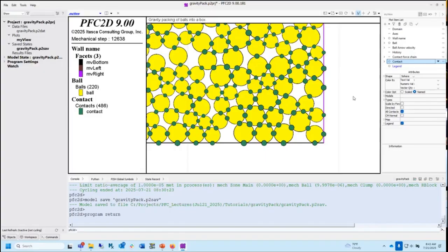And this doesn't necessarily correspond with overlap. Now, what if we take two particles and they're touching, so we have a contact, and now we put a bond in there, and now we move them apart, and the bond is really strong, so it doesn't break yet. So now there's actually a gap. They're not even touching, but they're still carrying a force because there's a bond. So that would still be an active contact.